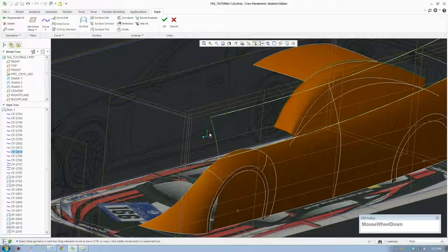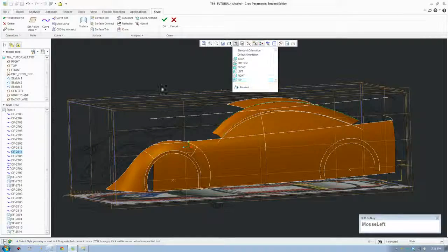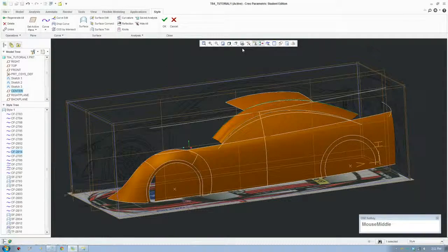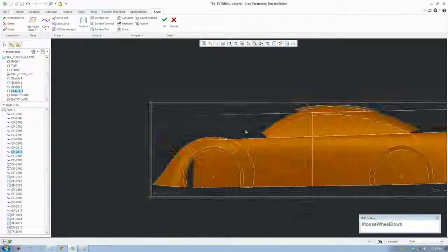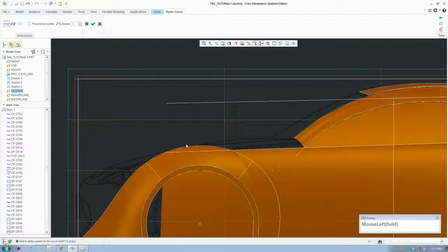Okay, I'm gonna start making the bonnet of this car. So I'll start by drawing the middle line. So activate the middle reference view. I know this surface needs to be extended all the way right in here because you gotta trim it off here and the surface finish nearly up to here. So it's a good idea to just extend your curve beyond what you need.